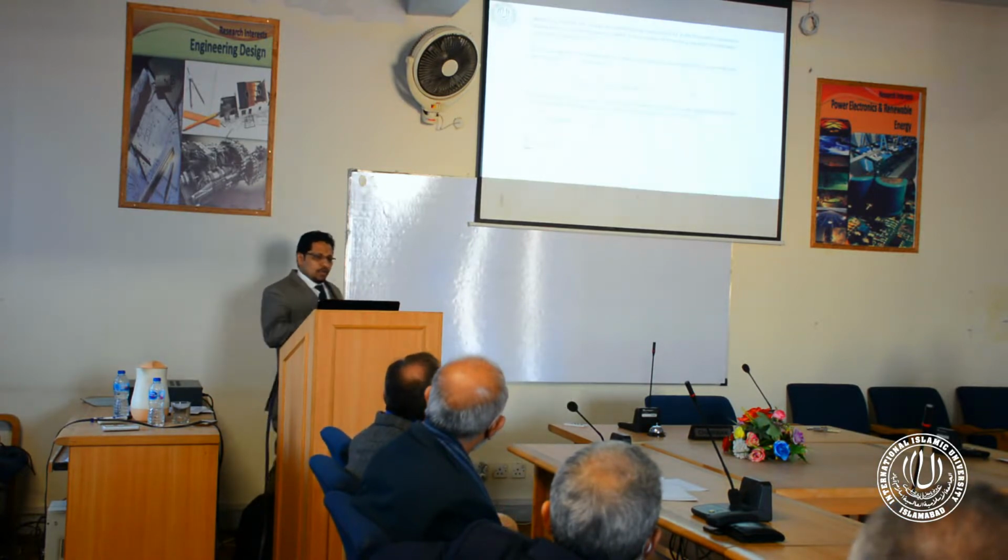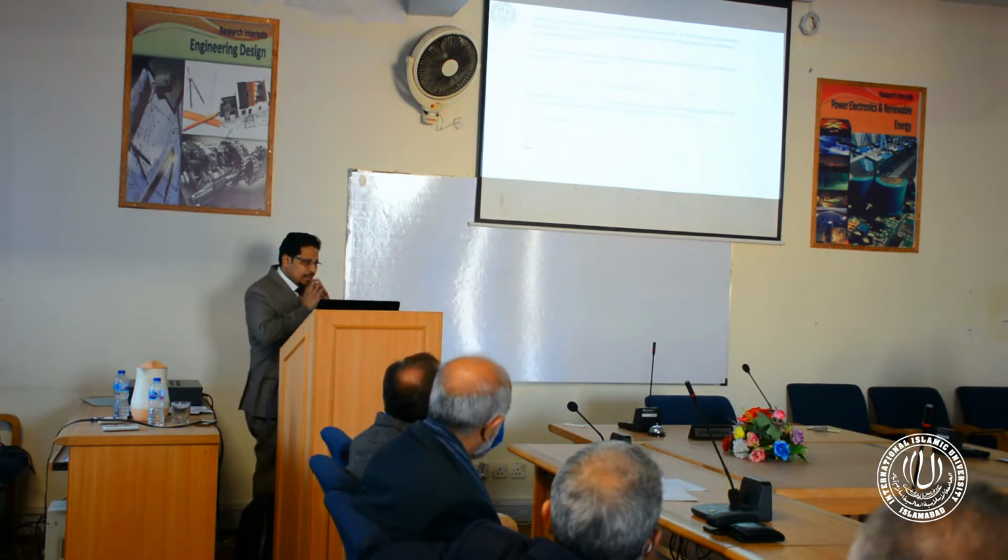So we check the orthogonality condition for that, and we give a threshold for each bit to be transmitted, so that if the value of this bit received at the receiver is less than a specific designed threshold, it is equal to 0. If it is greater than that threshold value, it is 1.